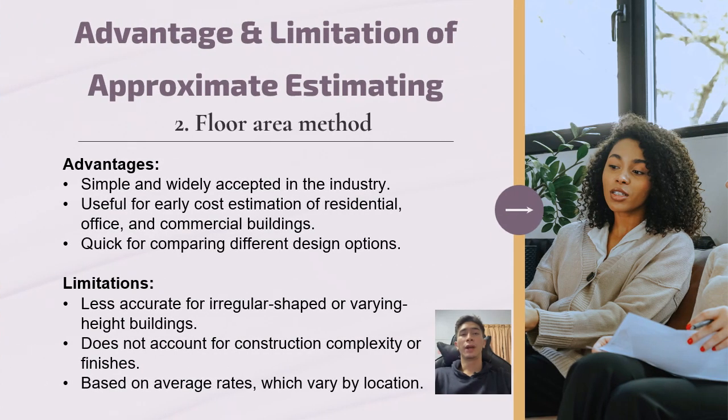As for the floor area method, it is widely used in the industry. The advantages are it is simple and quick to use, especially when only the total floor area is known. It is suitable for residential buildings, offices, and commercial buildings. It is good for comparing different building designs at the early stage.